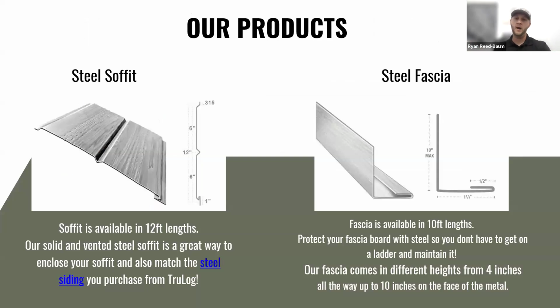We also recently came out with steel soffit and fascia. Again, very similar to what you may be out there seeing. It's a double 6 panel for a 12-inch coverage. We can do that soffit both in vented and solid. We are getting these products approved for the Wildland Urban Interface. That's really come out west here. Now, there's quite a few counties in Utah, quite a few counties in Colorado that are requiring it, and of course, being originated in California, we're trying to make sure that all of our products across the board can work with that. So we also do soffit and fascia. That soffit again comes in 12-foot lengths. We do our fascia in 10-foot lengths, and we can vary the height of your fascia board, whatever you need to cover there.